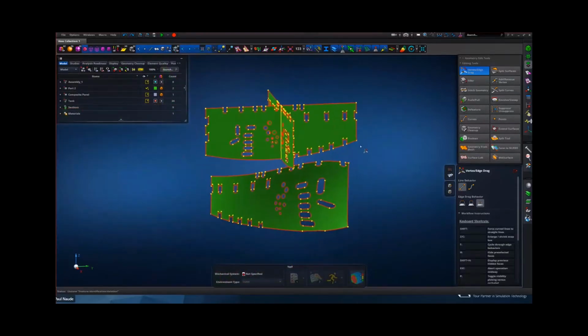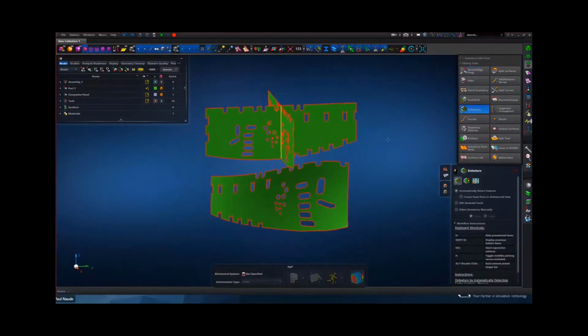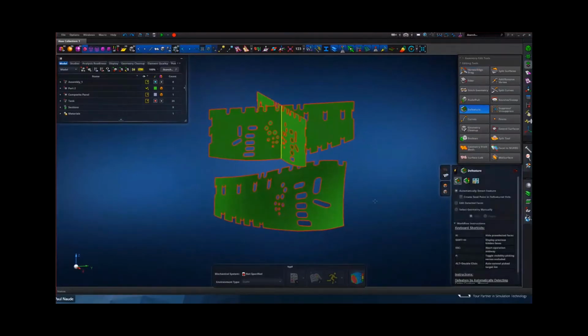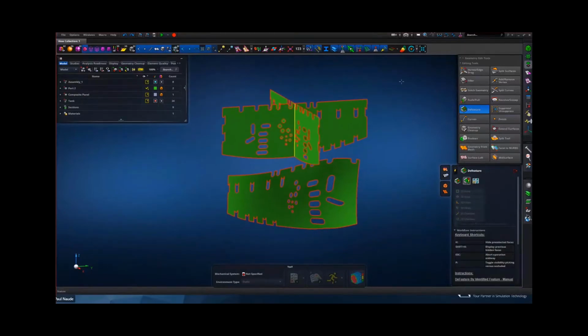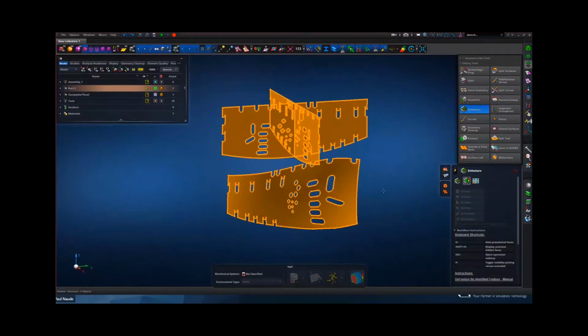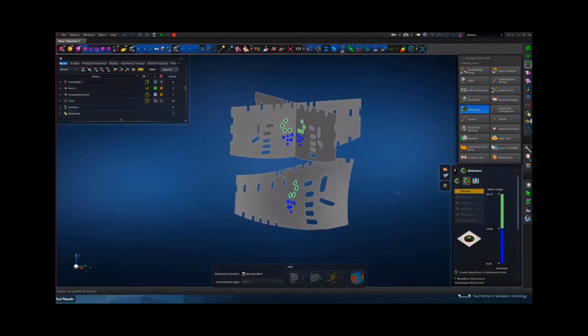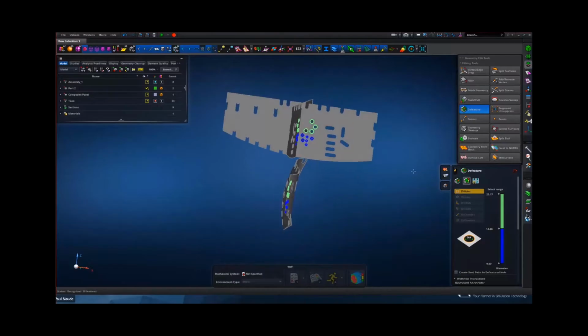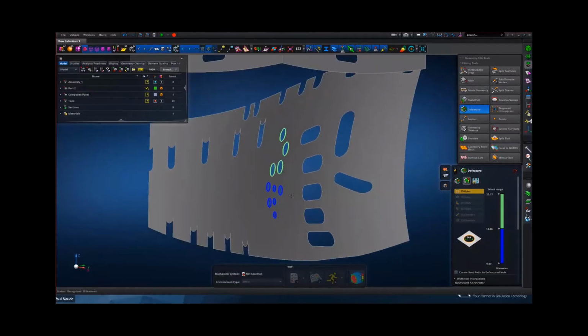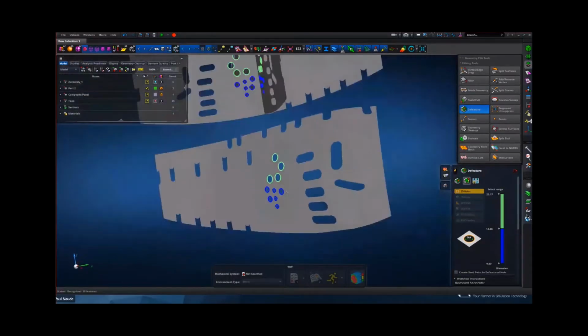and if you have hundreds of these to do, it's no fun anymore. So we have the geometry defeature tool that can identify features, set features. Like in this case, we can identify all the holes and sometimes fillets. Now, I don't have fillets or chamfers in this specific case, but if they were, they would have highlighted over here. So what this has done, it has identified all the two-dimensional holes, even on this double curved surface.